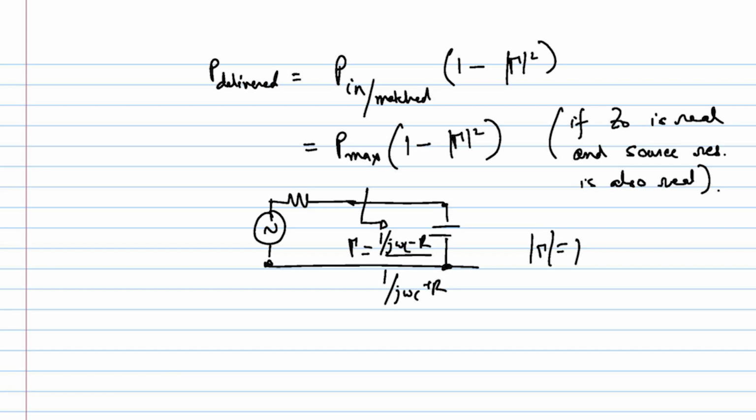And now let's turn our attention to something that you will see in many designs, and if you read research papers, you will often see the measure of a good match, whether the input is actually matched or not. One way to measure that is through the reflection coefficient or S11, right?